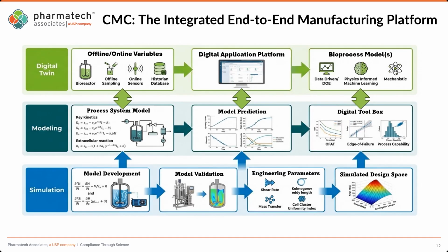The second layer would be the simulation, or running all the models together to represent the process in a mathematical and computational way. And connecting to the SCADA system, we would have a two-way communication, where some data could come from the SCADA and go to the models, getting some parameters updated in the models, and we can go back to the process for advanced process control. That is the ultimate level of the digital twin. So the combination of all of these would be very helpful for scale-up, tech transfer, optimization, and many different applications that we are going to show you in 3 case studies today.